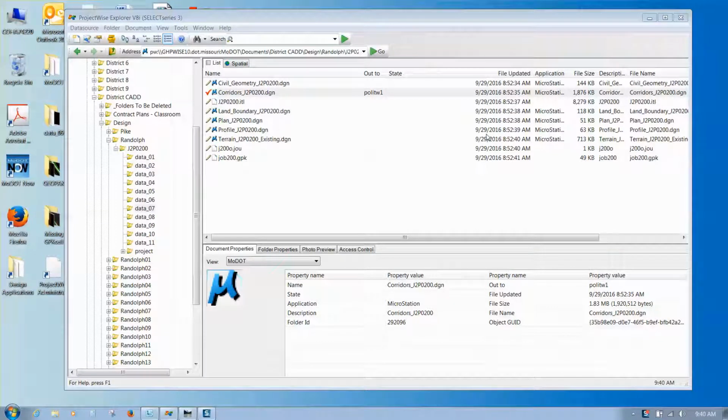Chapter 7 of Road 1, Superelevations. We're going to walk through the chapter where we create our superelevation sections, and we'll do some lanes, go along with that, calculate our superelevations, and then finally go back into a corridors file and attach that superelevation file and apply the supers to that corridor.